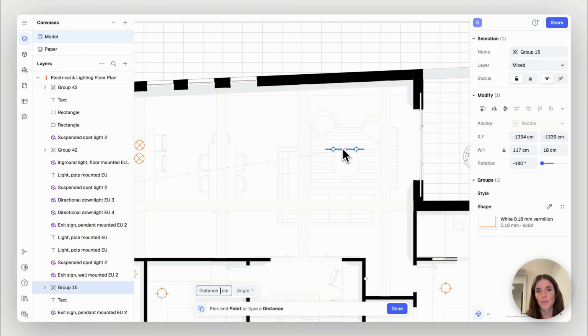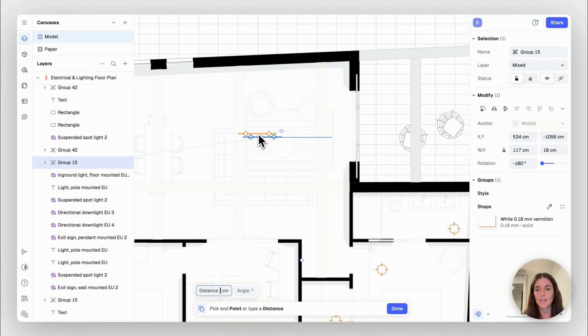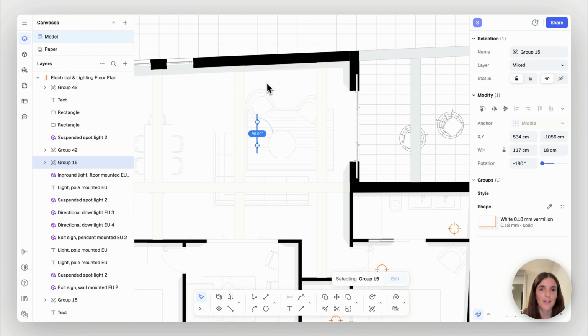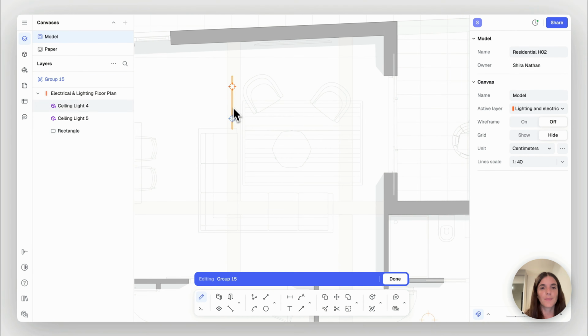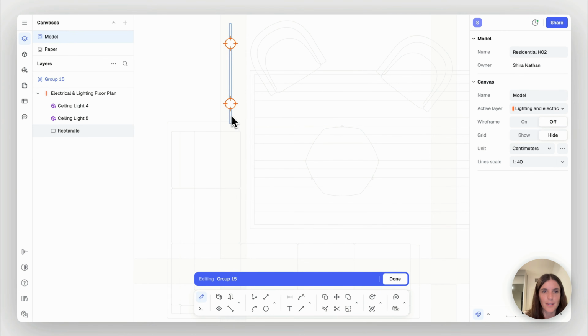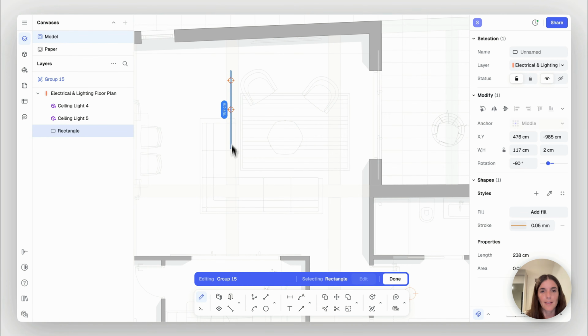And what I'm going to do, for this living room, is place these track lights along the beams, and I want to add some spotlights to them. So first of all, I want to edit this block. To do that, I'm going to double click it, and then I'm going to add some spots and edit this track light so I can make it longer.